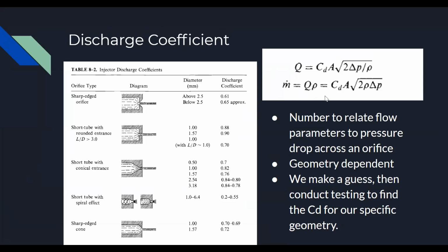So yeah, you start with mass flow, discharge coefficient, pressure drop, and density, and you calculate area. And then once you model that, you do the opposite, where you have your area, your mass flow, your fluid density, and the resulting pressure drop from the sim. And then you calculate the discharge coefficient, and then you go back and do that again, where you take the discharge coefficient you just calculated from the flow sim and find a new area.